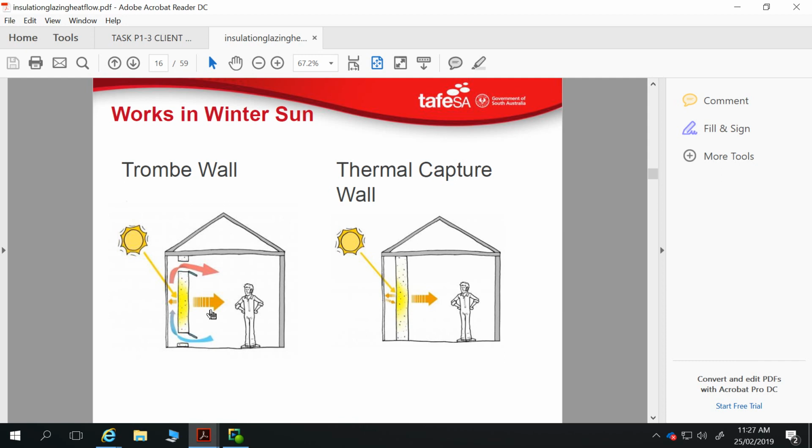because in the morning you can get that Trombe wall heated up, and then in the evening you can get that Trombe wall heated up in winter time, but still keep that relatively well shaded for summertime. But you really don't want to have thermal mass or this sort of situation happening on an east or a western wall, because typically they're going to be most exposed to that sun during summertime. When the sun's coming up in the morning from due east, it's going to be heating up that wall and heating up your house in preparation for the hot day ahead. It's not what you want.